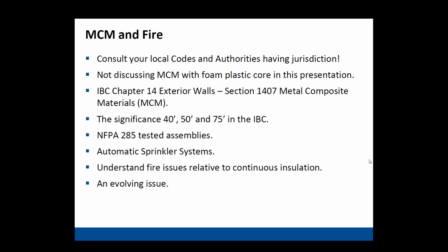I mean, maybe if the PE core just became an interior product, if it meets the interior fire criteria. The one thing that would be nice is if a lighter fire retardant core could be developed, because right now I think it's almost double the weight of the PE core. Still, in a 4mm panel, it's not a significant change, but it is somewhat meaningful. It's something you just have to keep in mind as a designer.